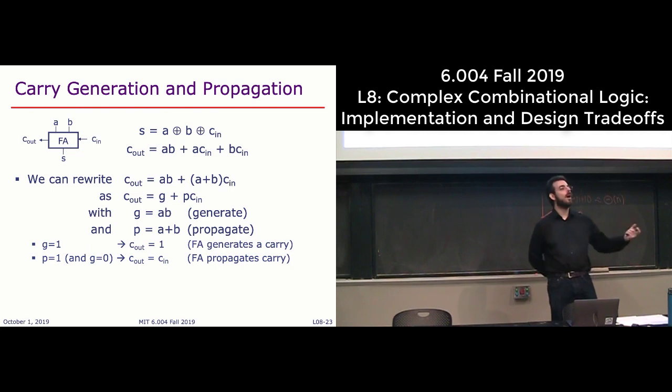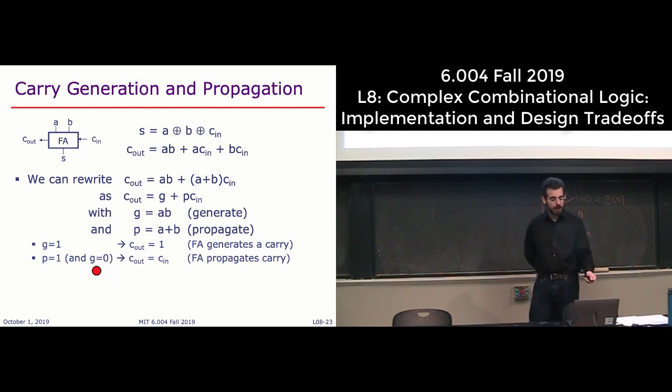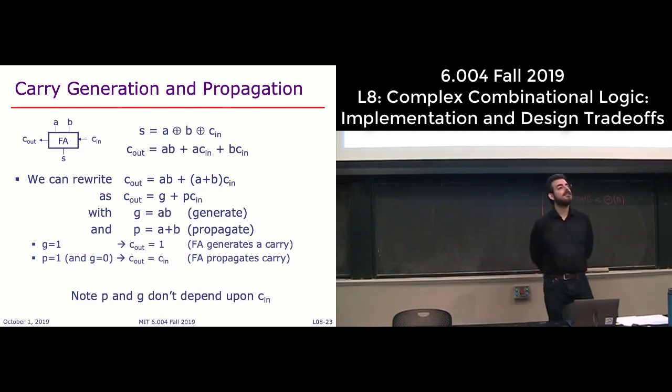The carry is going to be 1 no matter what the carry in is. And if P is 1, so if propagate is 1 and generate is 0, then the carry out is the carry in. We say that the full adder is propagating the carry. And note that these values don't depend on the carry in.